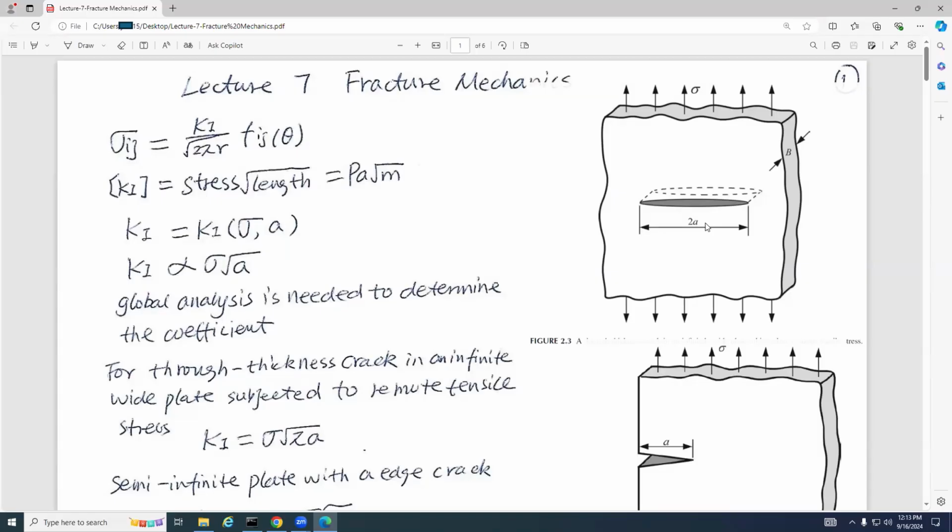Also epsilon. And what is the relationship between epsilon and sigma? The only relationship is the material properties, right? The material properties bridge the gap between epsilon and sigma. Because sigma is singular, this one is also singular. However, the displacement is not singular.